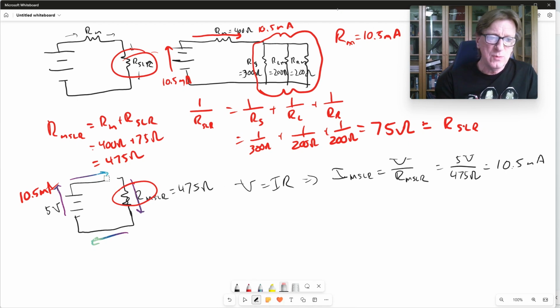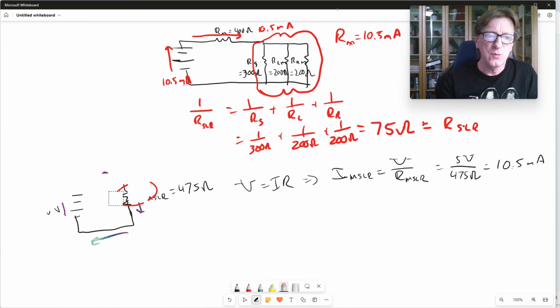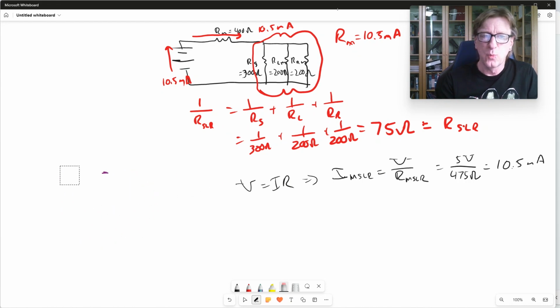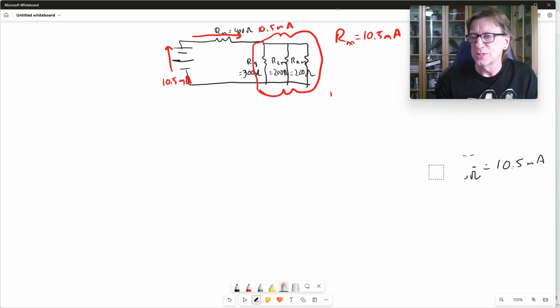let's take what we know then and let's find another loop. Because remember what our rule is when we're trying to find the currents, we always have to add one more component into the loop, one new component that wasn't in the loop before. This is how I managed to keep from reusing equations, which of course will just put me going around in a circle. It won't help me at all.